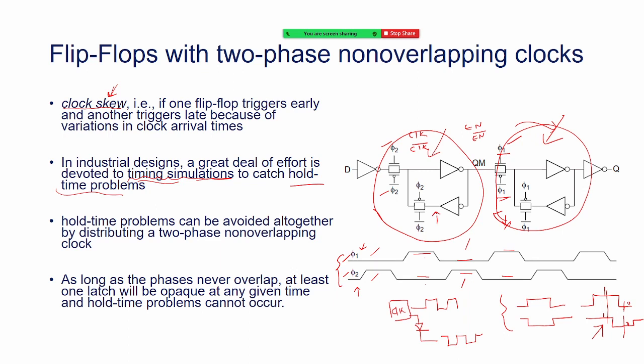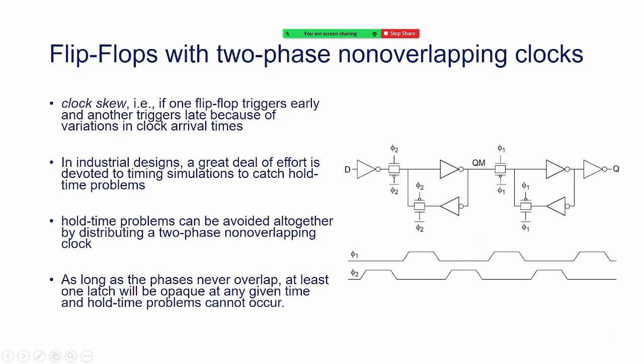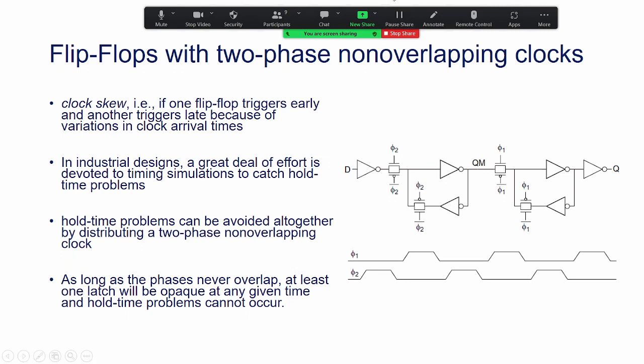In the edge trigger, we use a clock. In the D latch also we have a clock. Basically, what I personally think is we generally use flip-flops because most of the clocked circuits that we see in today's SOCs or anywhere are based on the transitions, not based on the levels. So that is the reason why flip-flops are used, and flip-flops may operate at higher frequencies, but latches may or may not, I'm not sure, operate at high frequencies. I personally think that's the reason why flip-flops are used over latches.